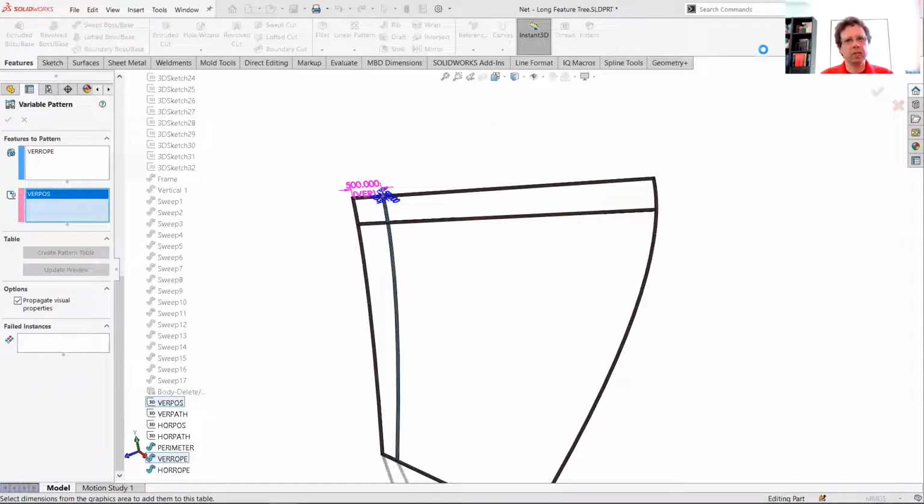So it will take you a certain amount of time to draw all those points, all those lines, all those sweeps. And the waiting time increases dramatically if you ask SolidWorks to create things that are impossible. Because as you know, SolidWorks has to fail only that instance while still validating all the other ones. So if by any chance I didn't really pay attention, which I didn't, and the last one was really outside of the domain that is possible to create, this preview is going to take a long time.